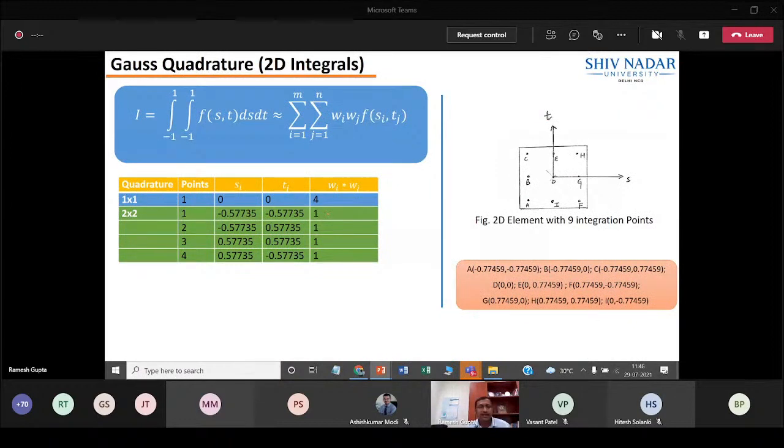And the same concept we can extend further for 2D also. For example, in case of 2D elements, it is the integral from -1 to 1, -1 to 1, of B transpose C B dx dy. That means here you have an area integral. Now, even this function you can evaluate at those Gauss points. For example, in this you have 9 Gauss points given. So you can have the lower order also, where you have only one Gauss point or 4 Gauss points, or 3 by 3, which we call it, where you have 9 Gauss points.